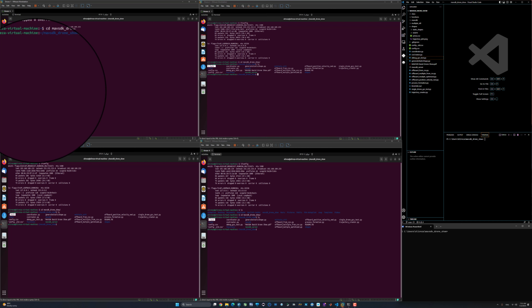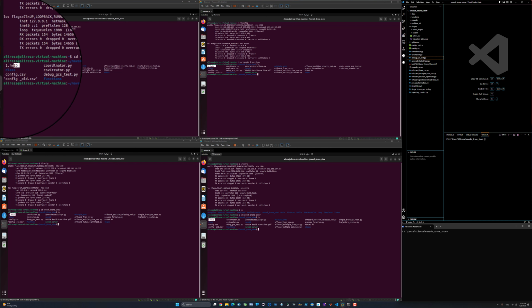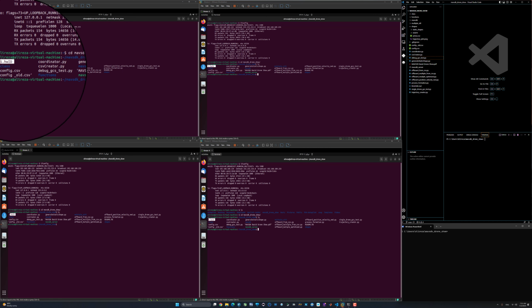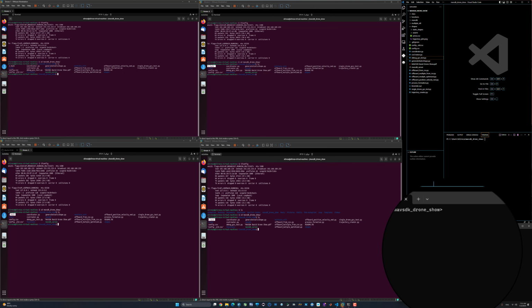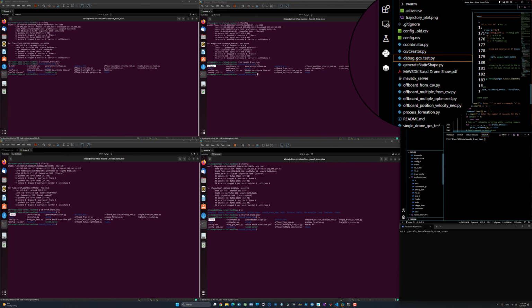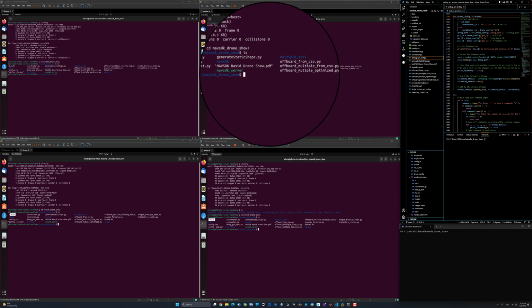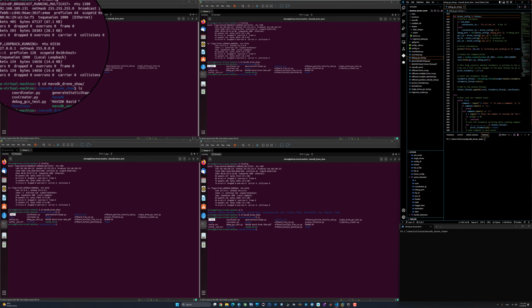This is an empty file. Only the name of the file is important, which is 1.hwid for drone 1, 2.hwid, and so on, and all of these files should be available near the coordinator file, so the coordinator knows which file it is using. On the ground station, you need to open the debug GCS test, and you can connect to the drones.